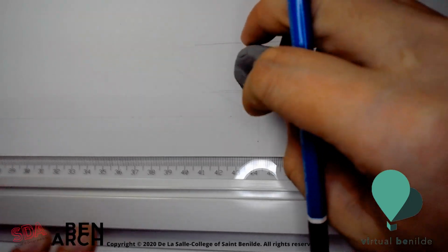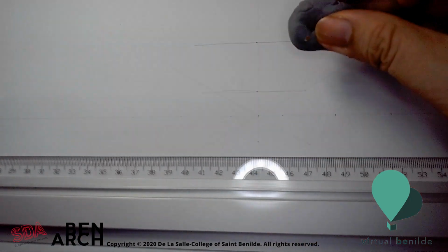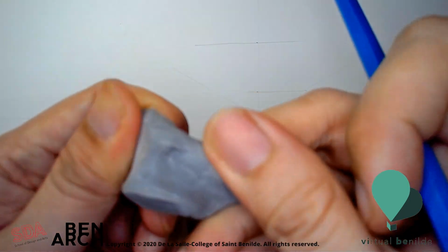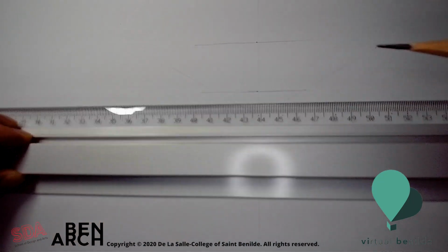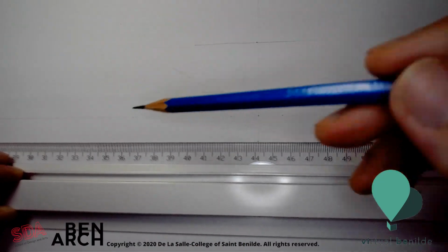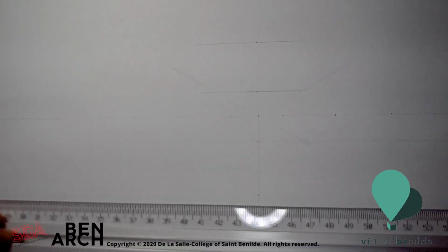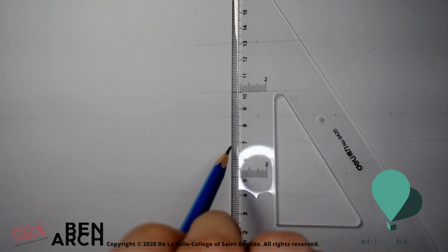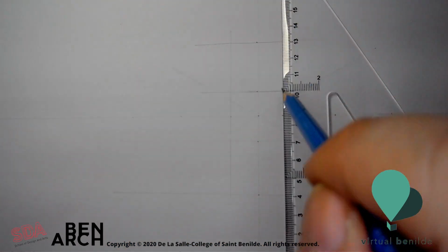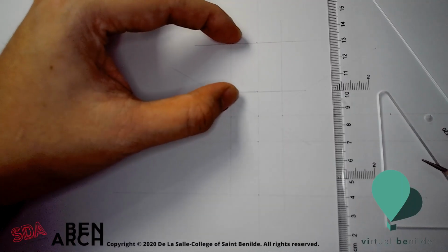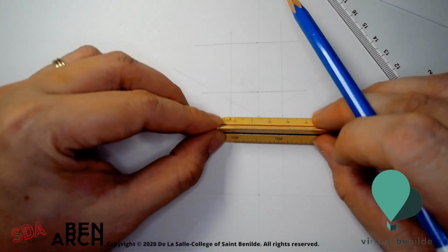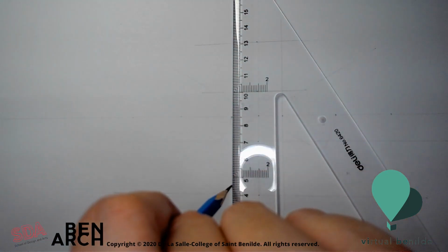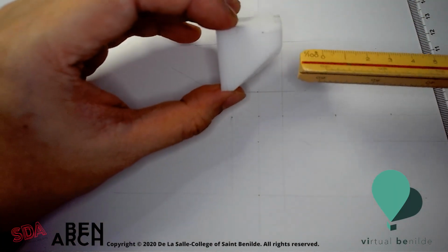So if you have a mistake, I'd rather you gently erase that line with a kneaded eraser, like so. Again, light as possible. So the elevation is going to be spanning over here, here, vertical lines. Create first these things. So I'm going to draw these out, these guidelines. So this is where there's maybe a mistake here. This is a bit off. So I'm going to erase gently. Has to be here. All right, so the top view is going to be something like this.